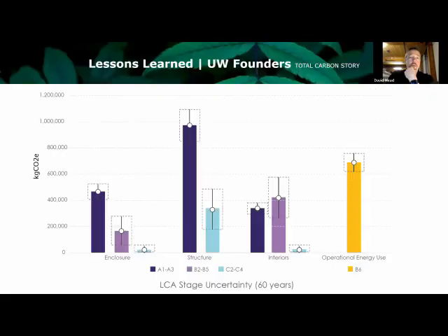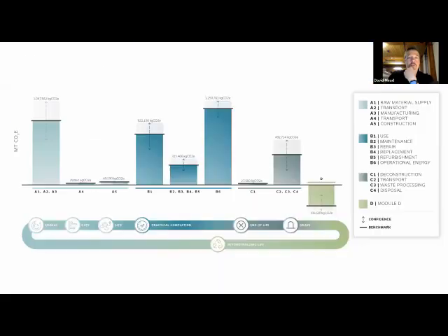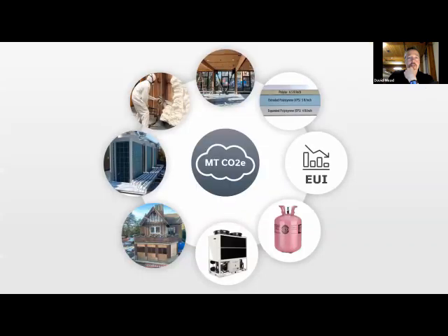Oh, foam, yeah. Well, spray foam, the historic renovation, right? Spray foam often comes up. The blowing agents, they're trying to show how to avoid that. I mean, polyiso's better. XPS was really bad. It's nice with the newer regulations on XPS. So yeah, that's helped a lot.